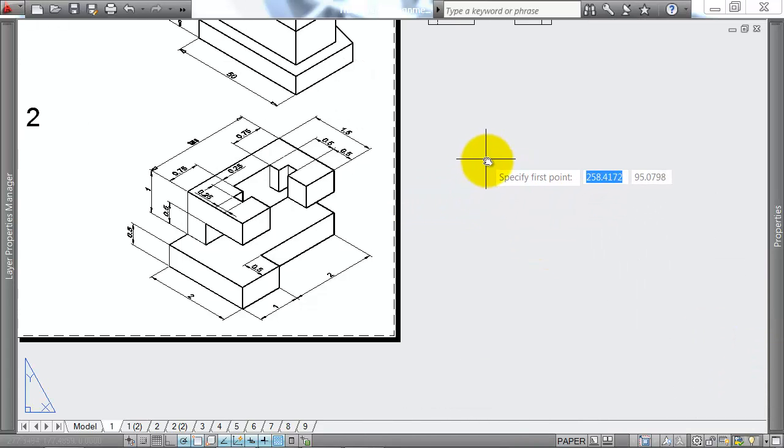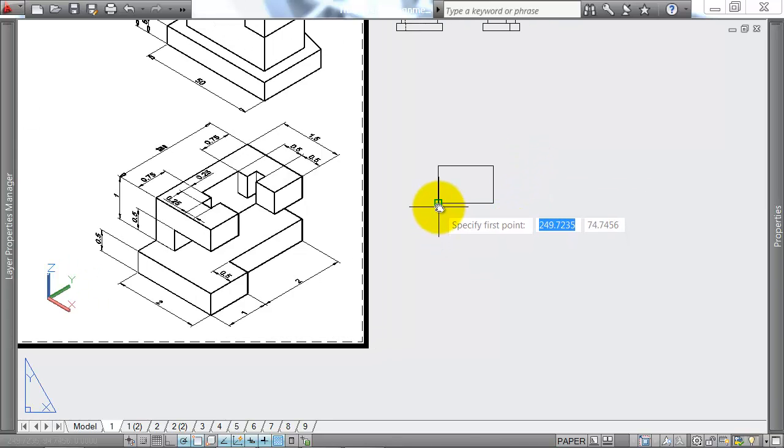So we've got 3 units across the bottom and 2 units tall. So I'm going to scale this up 10 times. So I've got 20 down and 30 across. Maybe I'll start with just boxes that all the views go in. So I can come across here. The height of this shape is 1 plus 0.5, so 1.5 units. By my scale factor, it's going to be 15.